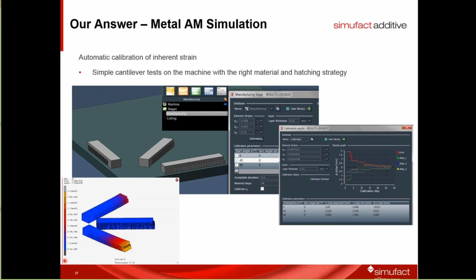You manufacture two or three of these little cantilever specimens using your hardware, with the power you're going to set the machine at, the speed you're going to use, and the hatch pattern you're going to use. Then you build one of these specimens, cut it off or cut it in between, and measure the deformation that occurs after you cut it off the base plate.